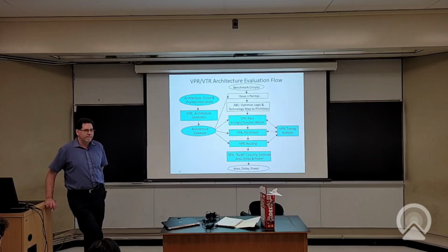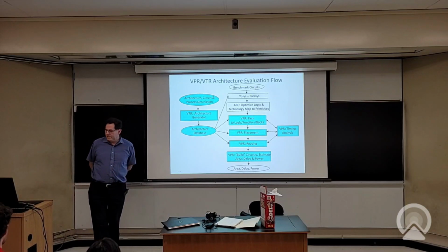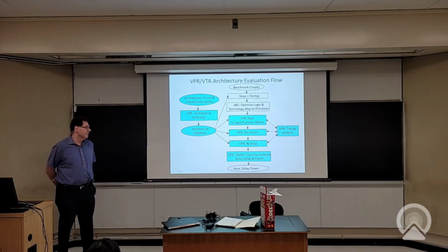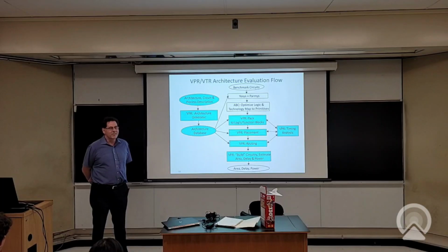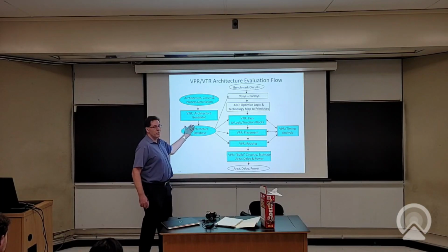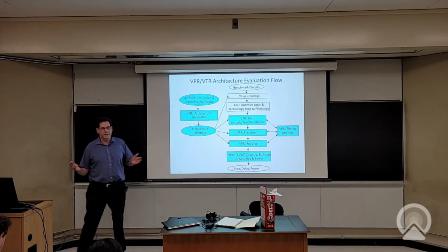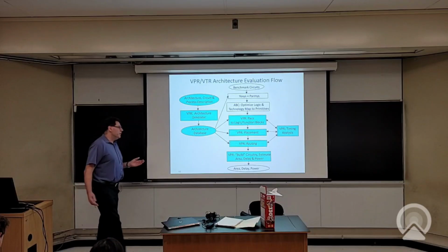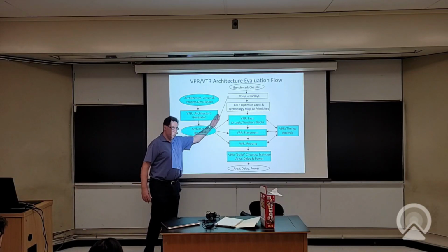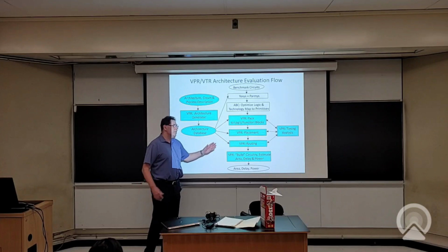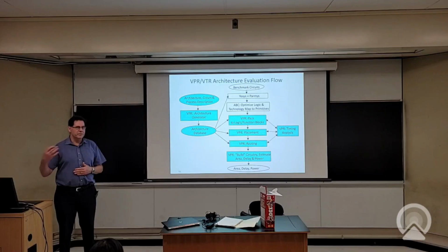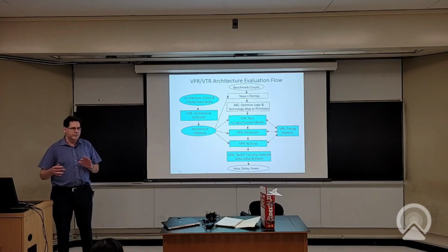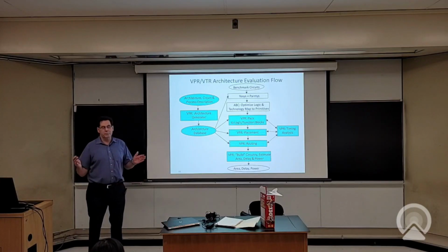There's also bias in the pack, place and route, for example. It was designed for an architecture, now we're changing it to an architecture it's never seen before. Yeah, so is there any way we can prevent that kind of bias? That's a good question. So not really. Basically, if your CAD tools don't optimize equally well for all architectures, and they generally don't, then your results are biased. You might have better architectures that you don't go and do. You try to fight that by making these algorithms quite adaptable. And if you change the architecture radically, you have to spend a bunch of time on the CAD tools. You have to expect that the CAD tools will be quite inferior for a while. You've got to go look at it, try to improve what they're doing, which does make those radical changes a lot more expensive to evaluate.